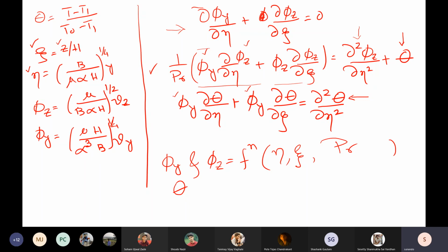So any term where Prandtl number appears, the effect of that will be, as you can see in this, rather small. And if I set them exactly equal to 0, what kind of a flow is that? There is a name for that kind of a flow where the convection is unimportant. We have been using that term again and again in this course.